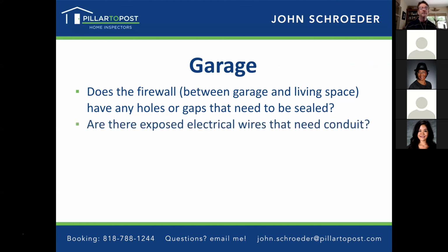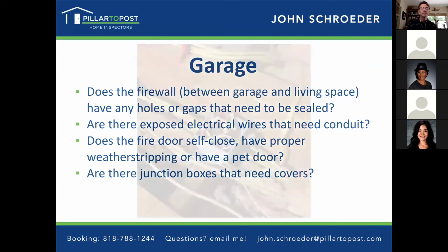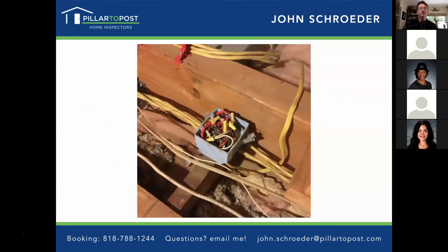And check to see if there are any exposed electrical wires that should be in conduit in the garage. It should have a fire door that self-closes. And make sure that there aren't any open junction boxes. Those are commonly seen in garages, also crawl spaces and attics, but those are a safety hazard.